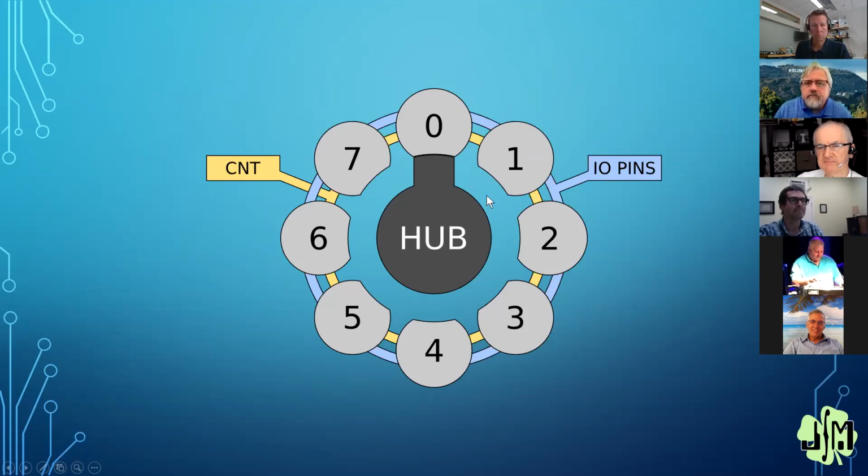On any given hub cycle, a cog may not need to talk to the hub, so nothing happens. It could, though, want this, say this cog wants to write information to a shared location in the hub. So let's say this was a sensor cog reading some kind of sensor, and it put it at a known location in the hub that this cog also knows and can pick it up. This is the basic mechanism in the P1 and probably most P2 programs for sharing information from cog to cog, using this shared space.